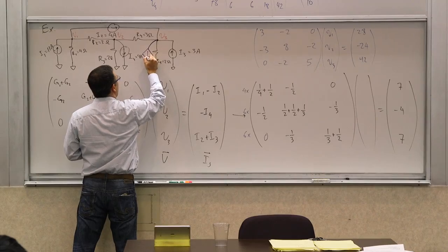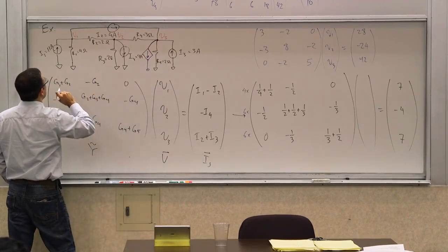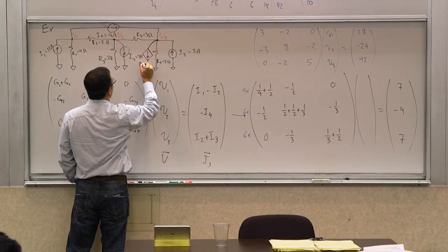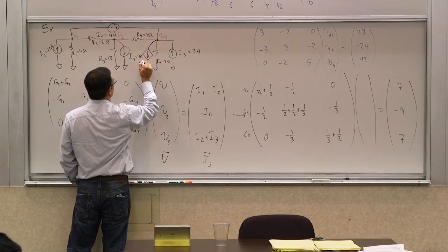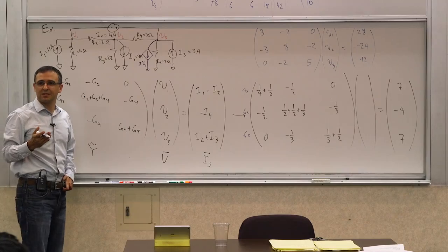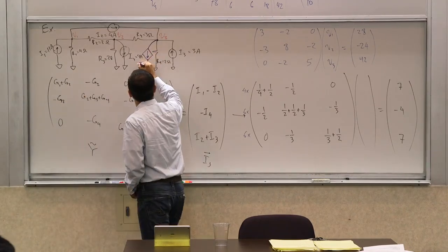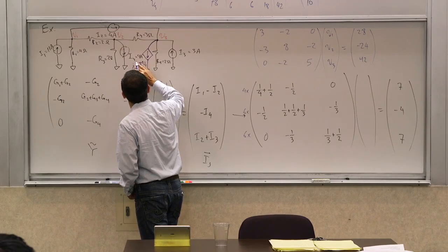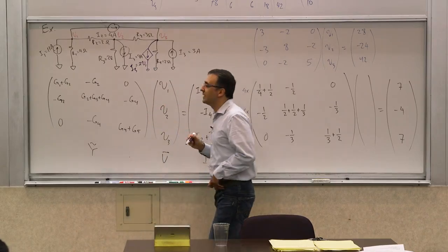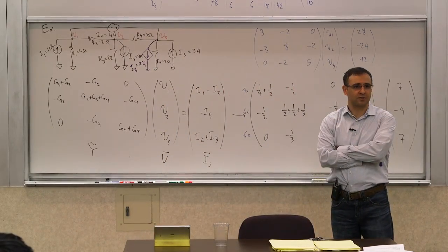So let's say I put a dependent current source here, which is proportional to this voltage. So this is going to be basically 2 times V1, so the current. Obviously, the units of 2 are Siemens, or 1 over ohm, because it's converting a voltage to a current. So what it says is that this current, you can call it, I don't know, I5, is going to be dependent on that. So now let's see how it's going to change our equations.